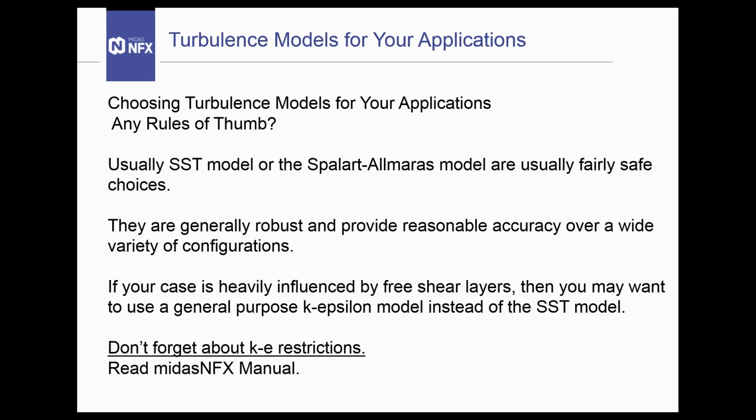If you are lost, or if you are analyzing a very complex model, you can use the shear stress transport model, which is the SST model, or the Spalart-Allmaras model, because usually they provide a fairly safe choice, and they are generally robust and provide reasonable accuracy over a wide variety of configurations.